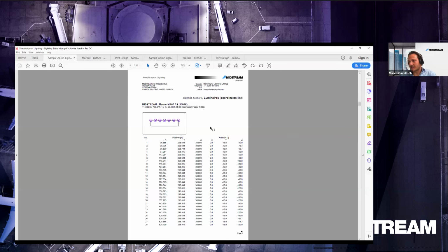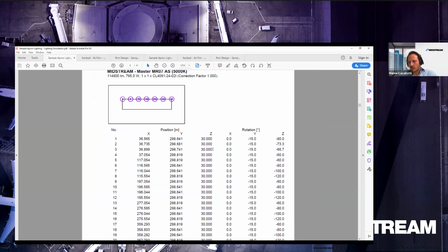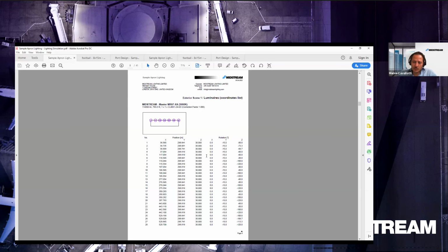The tilt is important. Sometimes it has a limitation due to some norms or local authority request. In this case, for example, the luminaires are tilted at 15 degrees. You see -15 here, only because the software considers counterclockwise rotation as negative. It depends on the photometric files. Sometimes it's positive, sometimes it's negative. You need to have an expert or the designer who has worked on the design to explain this to you.